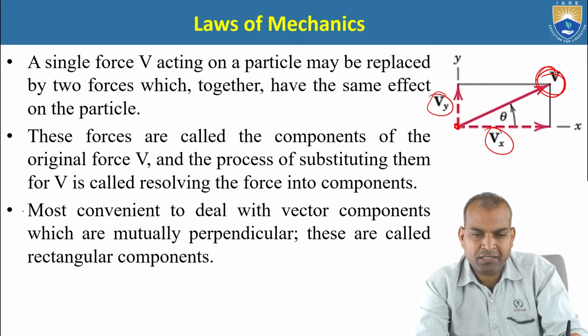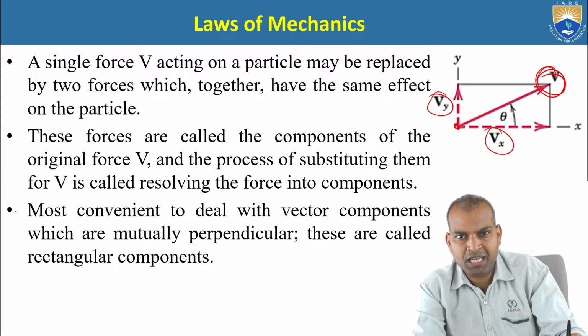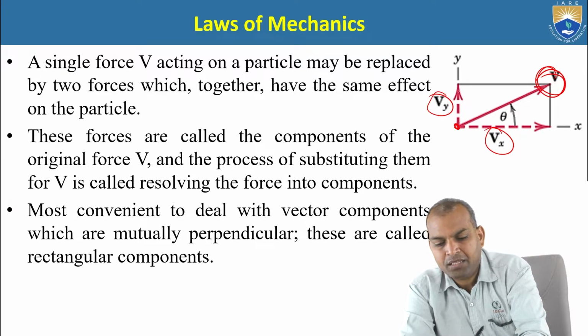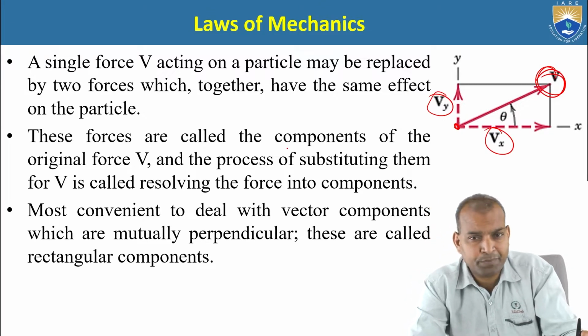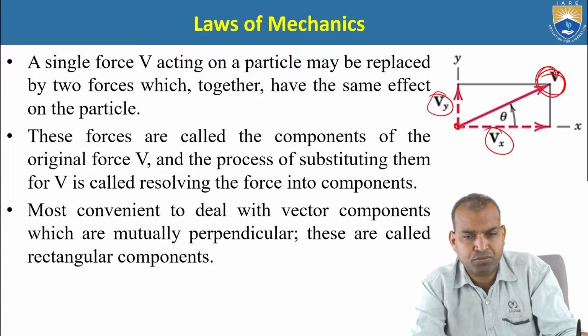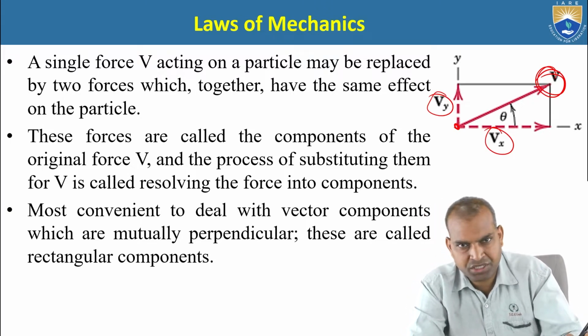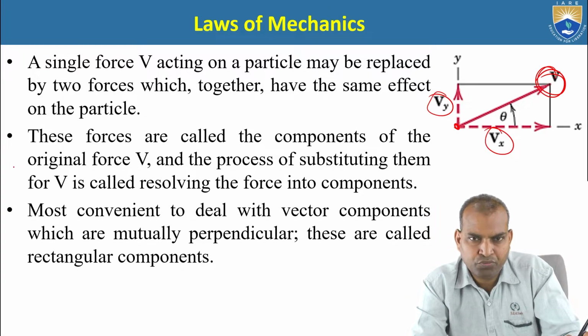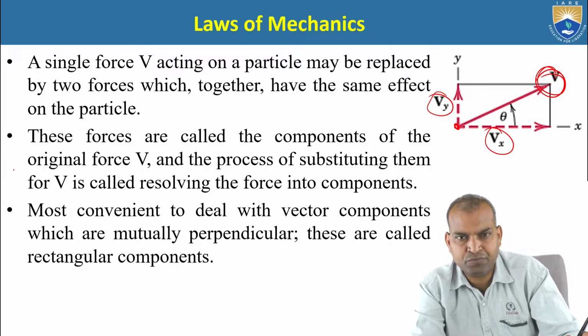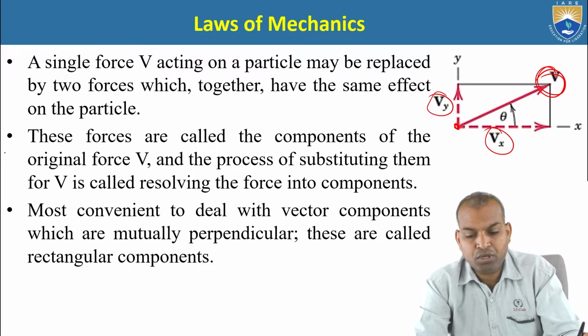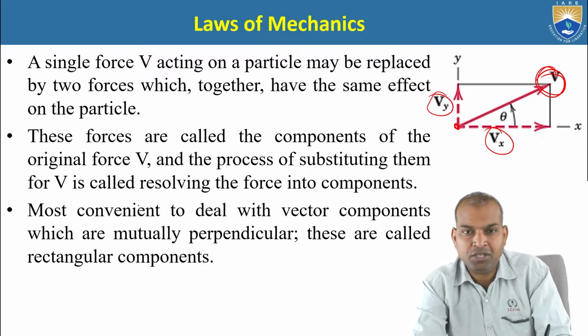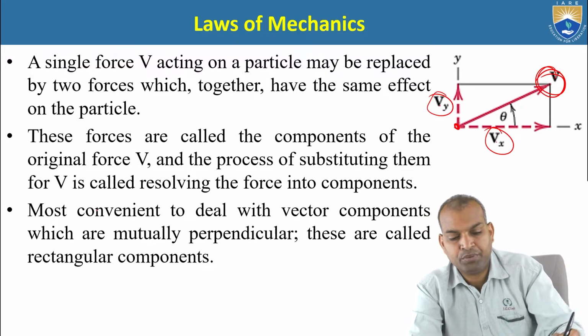Okay, so it is the reverse of the parallelogram law of forces. There, for Vx and Vy, we drew the parallelogram and joined the diagonal. The diagonal represents the resultant of the forces P and Q. Similarly, now suppose the force is acting with some inclination. To find out how to divide the resultant force into two components, Vx and Vy, one is the horizontal component and another is the vertical component.